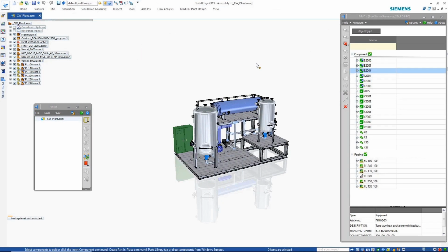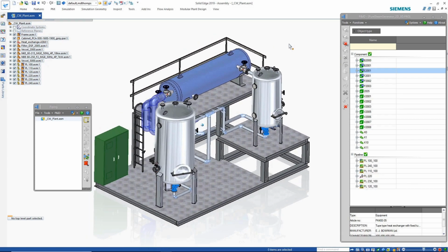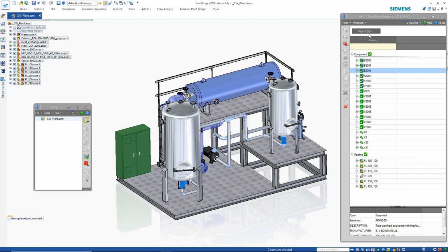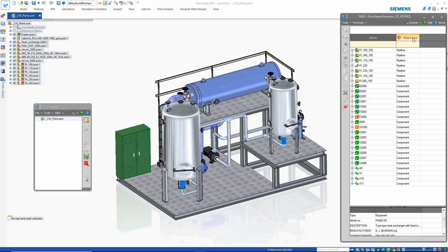What I'm then going to do is go into our model again. We now want to update our P&ID list sheet on the right here of the model. And we click refresh from P&ID project. And what we should see is in the P&ID list, we should see some new components marked in orange that were added to our number 2 P&ID sheet. And we're physically now going to add them into the new model.